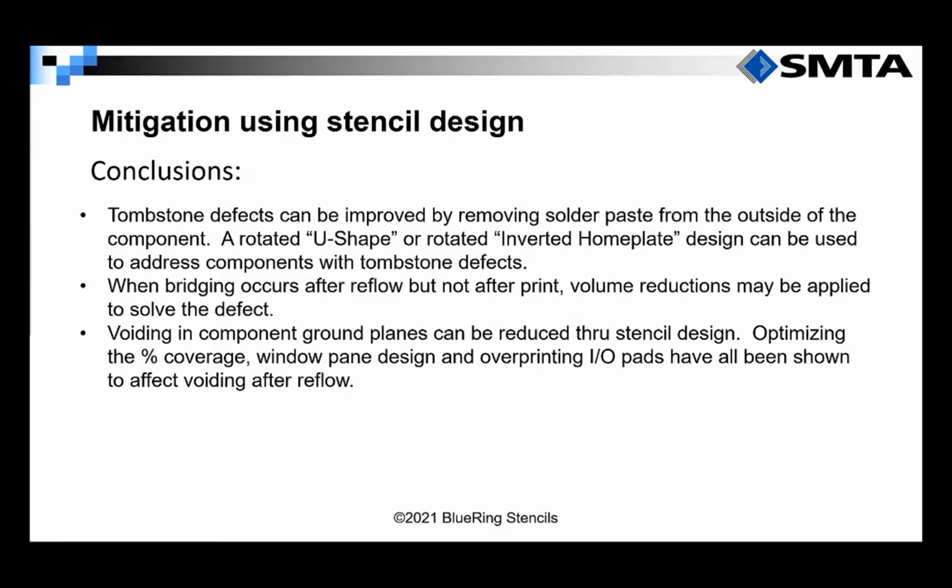And finally, we talked about voiding. Voiding in component ground planes can be reduced through stencil design. We've got to optimize the percent coverage. We've got to get as much solder paste volume as we can without causing float and skew, but we also don't want to print too close to the edge of that copper ground plane. So we don't want to get any solder splatter or solder balls happening in there between the ground plane and the I/O pads. And all these have shown that we can reduce voids, and these are just tools in our tool belt that we can use when we need to.